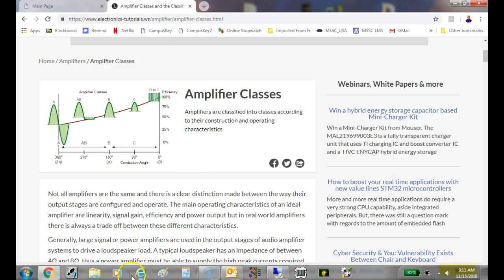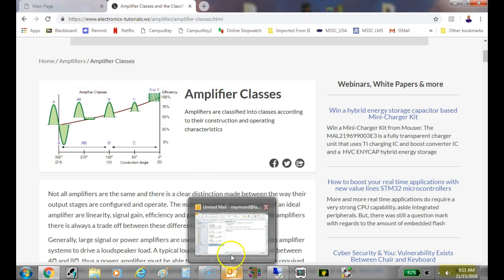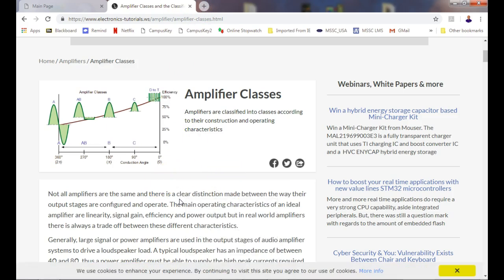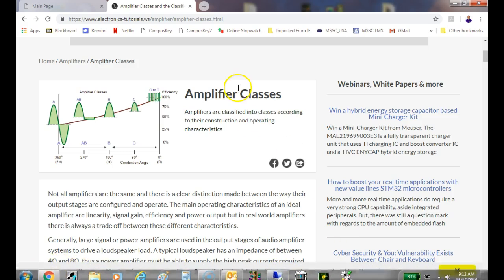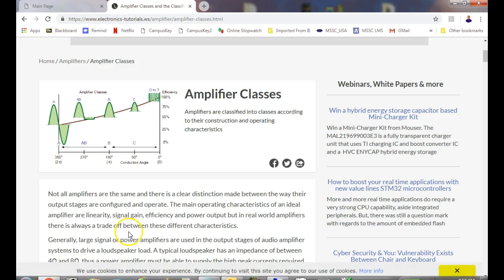What we do, guys, is we have to understand these amplifiers are usually designed for, except for switches. We know switches. Switches are basically just current amplifiers, right? You understand that? But a switch, we either cut it on or we cut it off, or technically we call it saturation and cut off. We don't operate switches in what we call the active region. When we get into the amplifiers that we're playing around with right now, these are what we call Class A amplifiers. So what that means is no matter what type of AC signal we put into these puppies, we're going to get an image of the AC signal out.